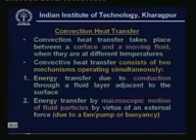And the layer close to the plate, as I said, is stationary. So the mode of heat transfer through the stationary layer has to be obviously conduction. So initially we have conduction heat transfer taking place from the surface to the fluid through a stationary layer. Then heat transfer will be by the bulk motion of the fluid particles. So the second mechanism is energy transfer by macroscopic motion of fluid particles by virtue of an external force.